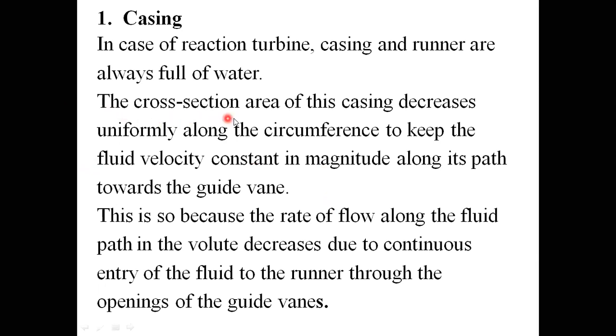See, the cross-section area of the casing decreases uniformly along the circumference to keep the fluid velocity constant in magnitude along its path toward the guide vane.